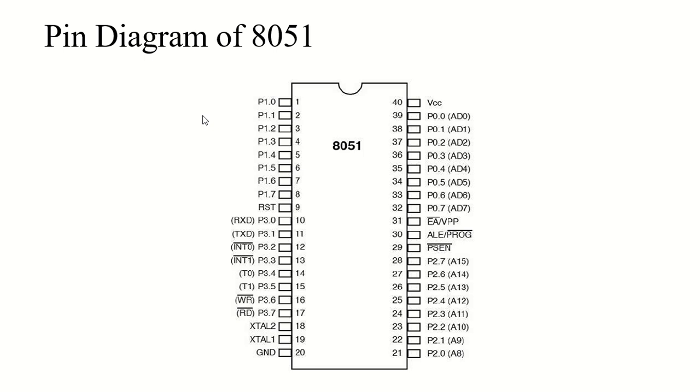We have discussed that in detail as well. And we have read and write signals for external memory connections in 8031 based systems. Sometimes in systems which are based on 8751 and 89C51, pins 3.6 and 3.7, the read and write pins, are used for input output, while the rest of the pins in port 3 are normally used in alternate function roles.